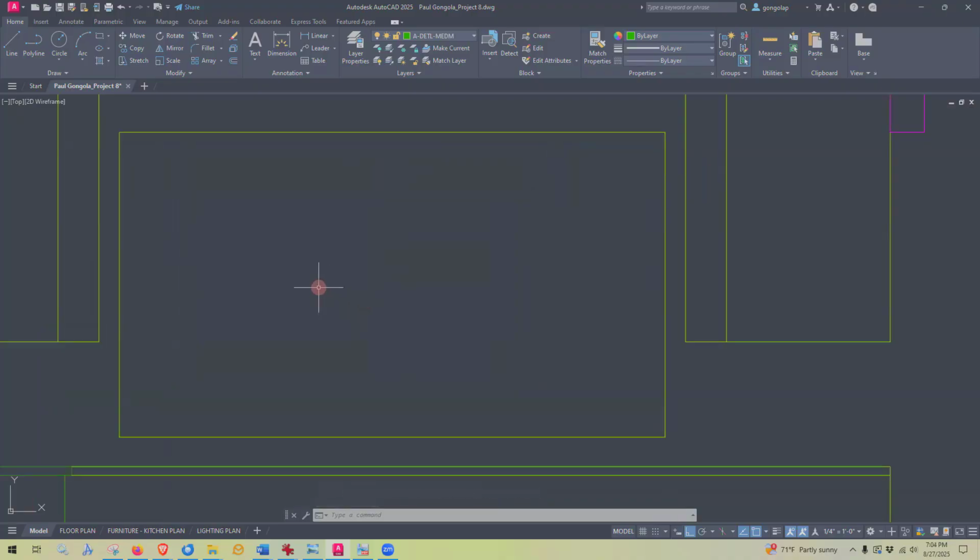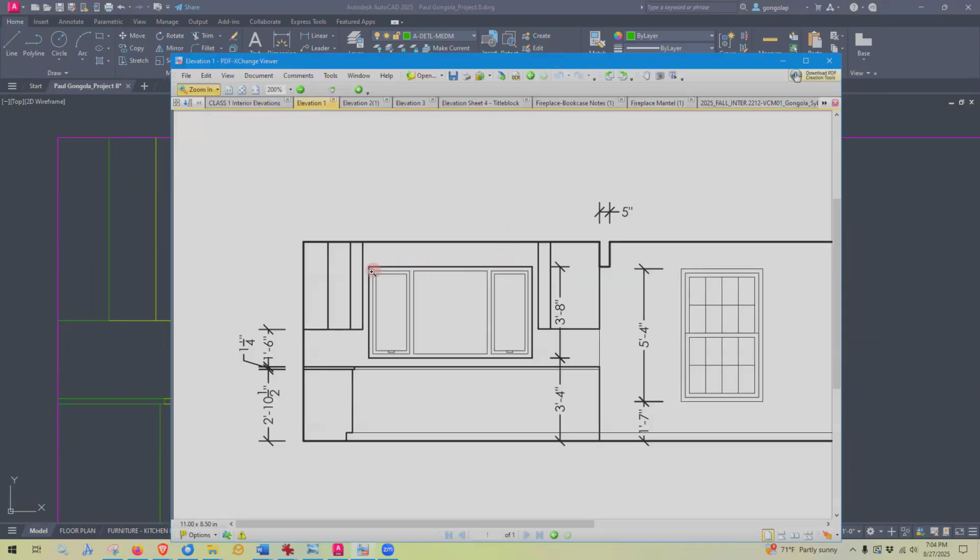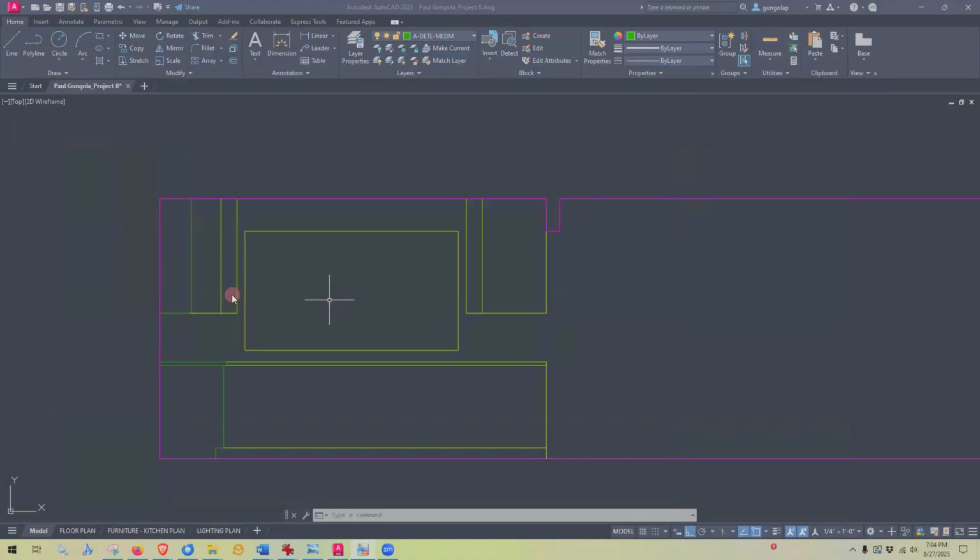And then, to minimize my offsetting, let me just bring this back again. So I've got to draw the 2 inch window frame here, and then I've got these mullions here. If I offset in 2 inches, I'm going to have to trim at these corners, and that would be totally fine. But what I'm going to do is use join to join these four lines, and then offset in, and that will clean up these corners for me. So I'm just thinking ahead and trying to make my life a little bit easier.